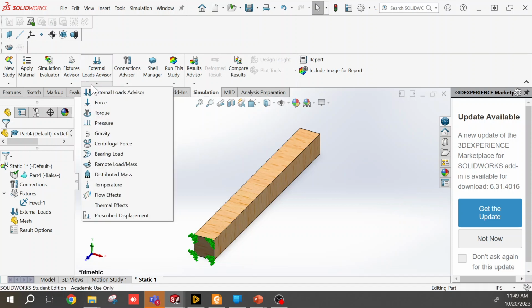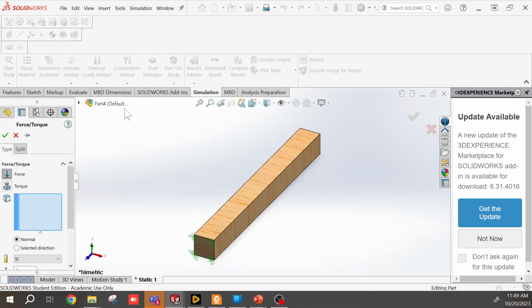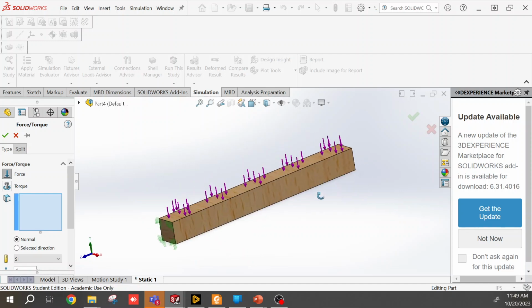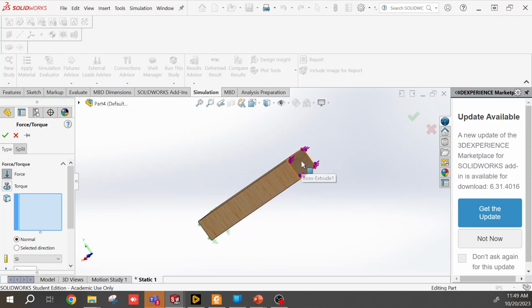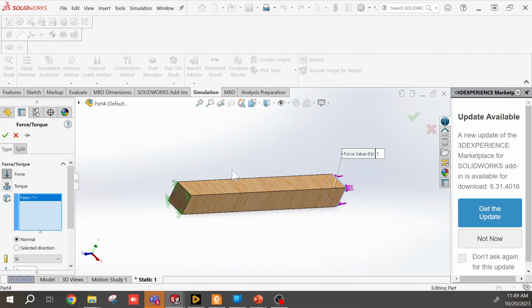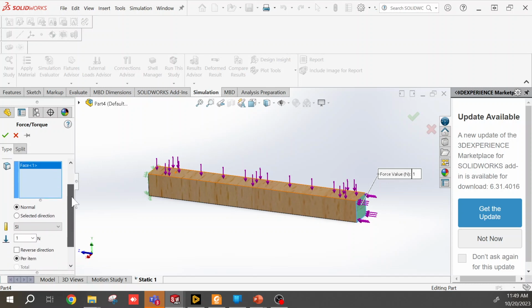On the other end, we want to apply a force. So I'm going to go to external loads, click on force, and you can see we're confronted with some options here. We can do a force, we can do a torque. But the most important thing you need to understand is that you have to define not only what direction the force is in, but the magnitude, and the surface or geometry it's acting on. So you can see when we hover over something, it's going to show us, do you want to apply the force there? We actually want to apply it at the end. But is that the correct direction that we want to apply the force if we're looking at a diving board type scenario? The answer is no.